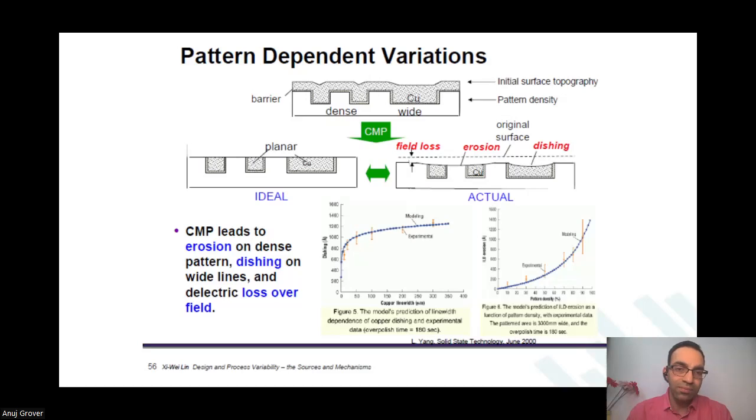Sir, the precharge line, you mean the clock that is going to the precharge circuit in the sense amplifier, that you route to connect the gates? Yes. So that metal is very sparsely placed. There is no other metal wire within 1 micron of it. That versus the word lines in the array region. Will you say that these two lines are matched?